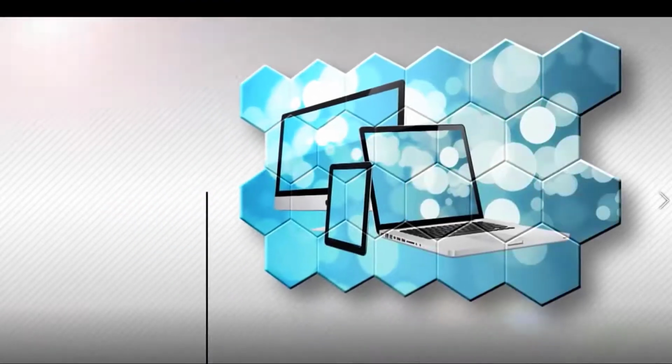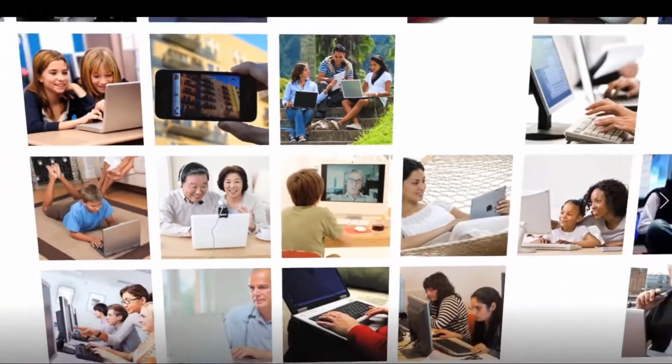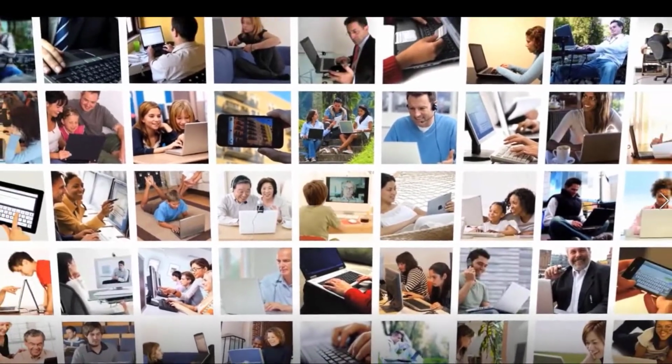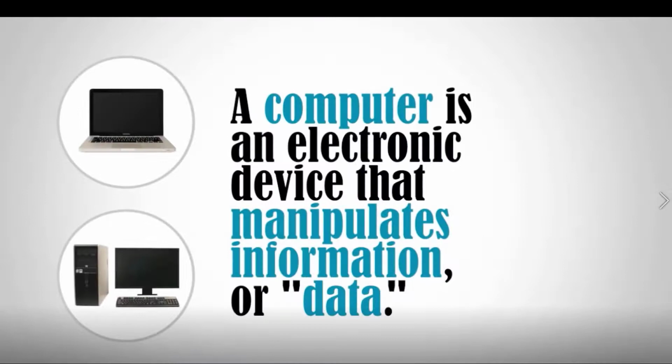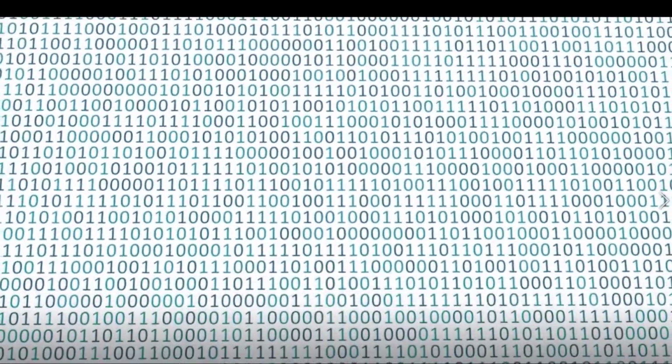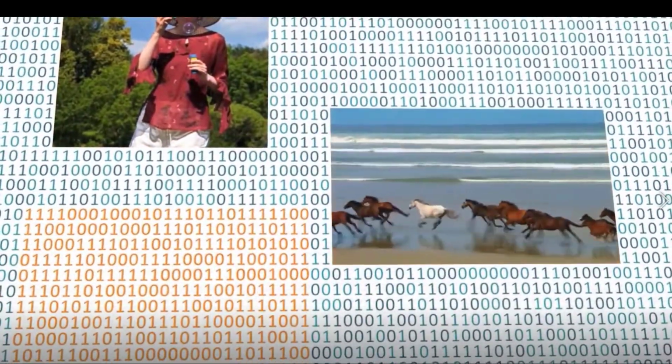The name of this course is Introduction to Logic Circuits. A logic circuit is the same thing as a digital circuit, and digital circuits are the building blocks of modern computers. The term logic or digital means that the circuit is built to operate on inputs that can take on only one of two values. That's what makes it logic. So it's like on or off, true or false, or ones and zeros. These circuits take in ones and zeros and produce outputs that are ones and zeros. A circuit that operates on ones and zeros is very simple, but if you put a lot of them together, you can create very complex systems.